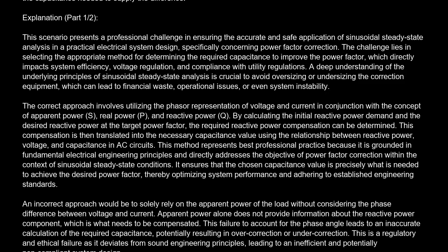The correct answer is D. Calculate the initial reactive power demand and the desired reactive power at the target power factor, then determine the capacitance needed to supply the difference.